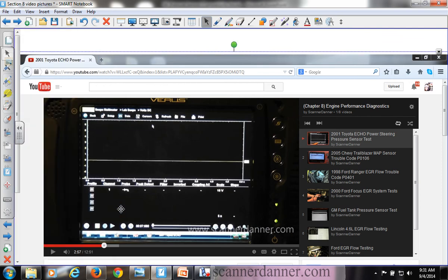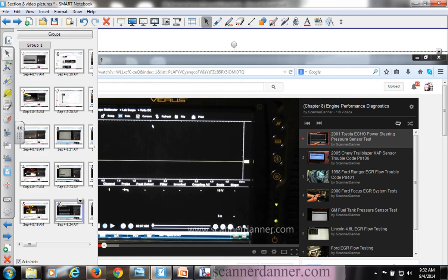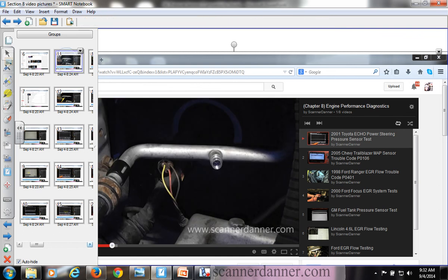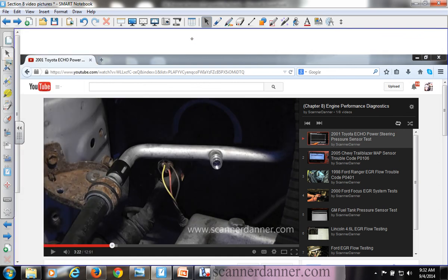What did I do? Went down to the signal wire and I read 0 volts. That's this one. That's a flat line 0. Next image, showing the sensor wiring, 5 volt ref, signal and a ground. Probably had a wiring diagram that I was looking at. If you watch the video, it's more complete in showing that. I know which one my signal wire is.